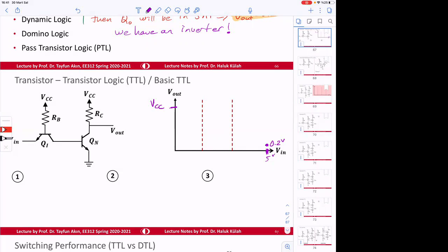If it is okay, maybe I can just talk about the first transition point. So if this was 0, this transistor was in SAT, and then this voltage here is how much? I need an answer from you. 0.2. 0.2 volts. Okay, so if this is 0.2 volts, that's not enough to turn on this. So QN is off.